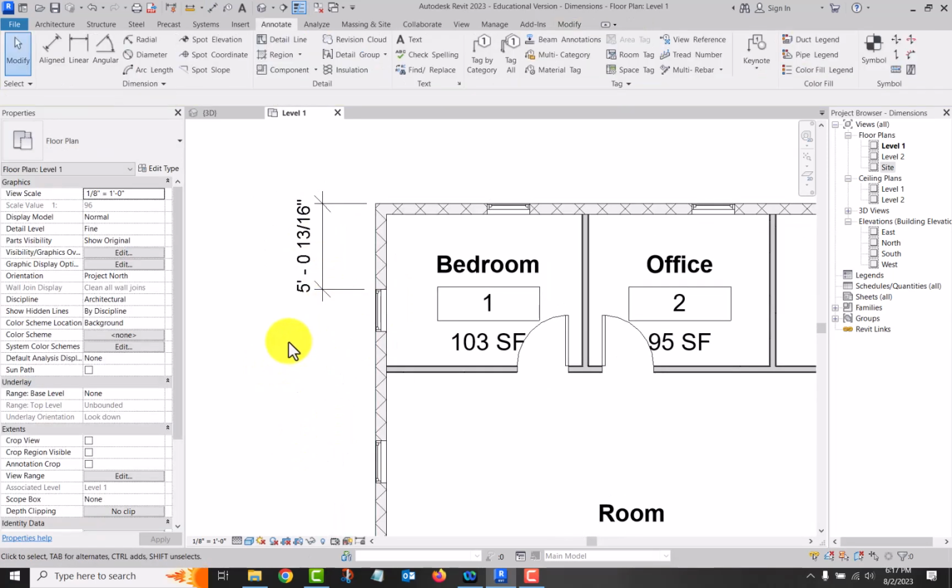And if you're dealing with CMUs, those things are modular in 8-inch increments. So everything, openings, corners and things, should be modular to 8 inches. It doesn't always work out that way, but that is good planning. And other than sometimes in this course we'll have a little bit, none of our projects involve CMU walls. Well, I'll take that back. The 1133 project does, but that's a year away, so you're okay.